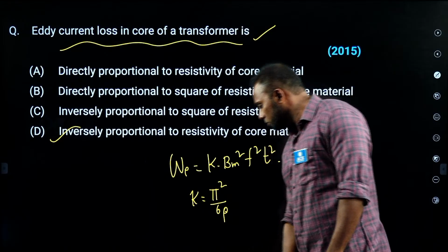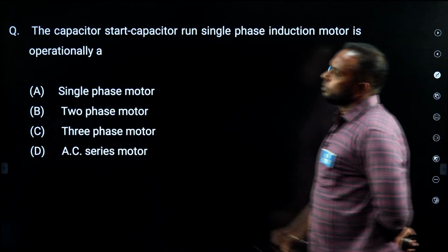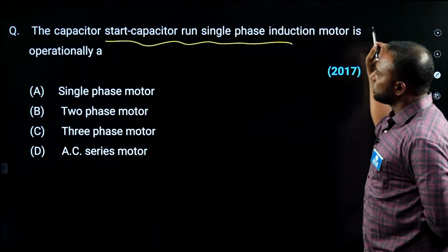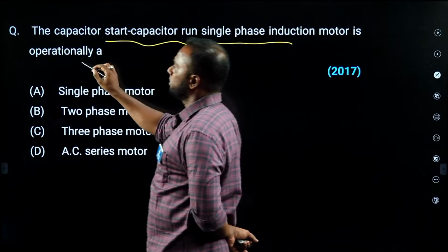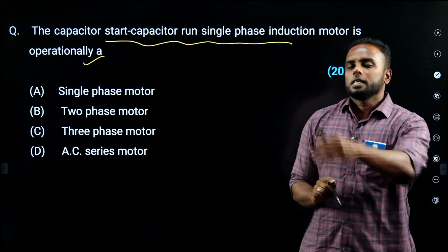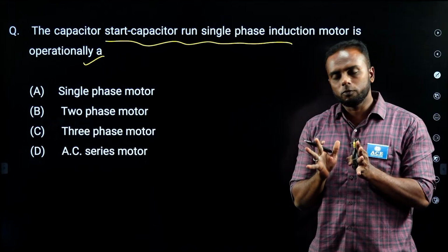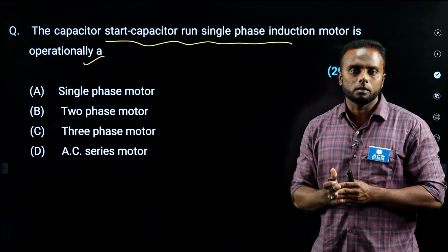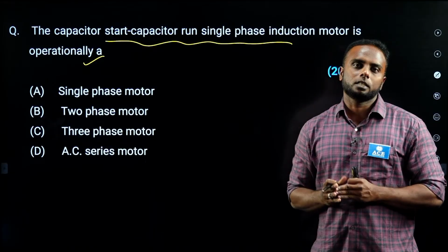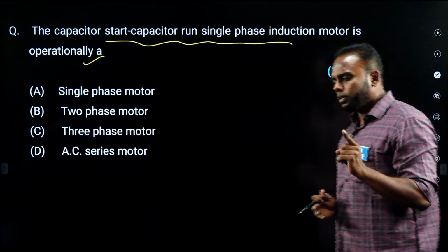Okay, next question. Series question. The capacitor start, capacitor run single phase induction motor is operationally a dash. Operationally, if you think, whenever supply is given, during its operation, it is not operating like a single phase induction motor, it is operating like a two phase induction motor.